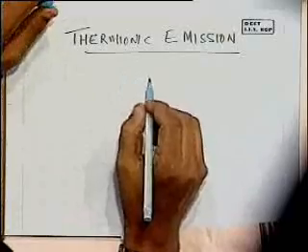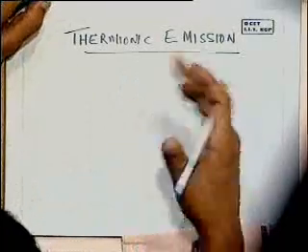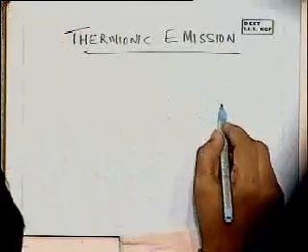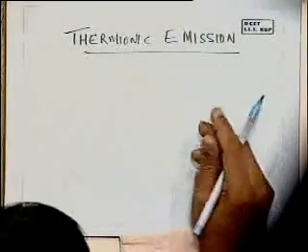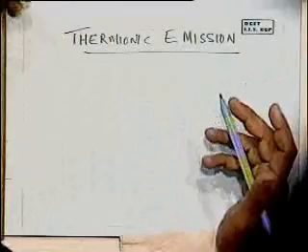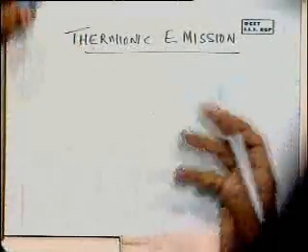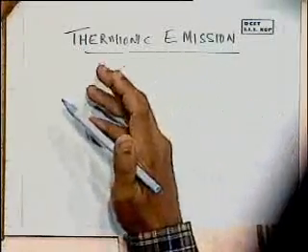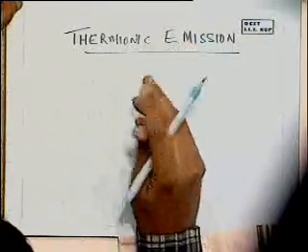Thermionic emission and vacuum tube devices. There is familiarity on this topic, so just a quick word from what we did last time. If the electron within the crystal has enough energy, more than the work function, it can come out of the crystal with enough thermal vibrations. But as it comes out, it leaves behind an effectively positively charged area. So there's a self-limiting condition. After some time, no more electrons will come out because there's now positive charge. They'll simply be sucked back.